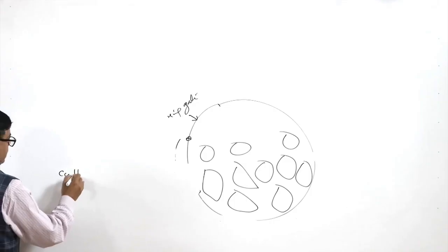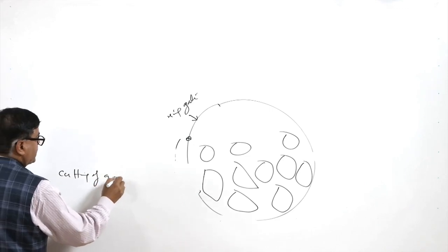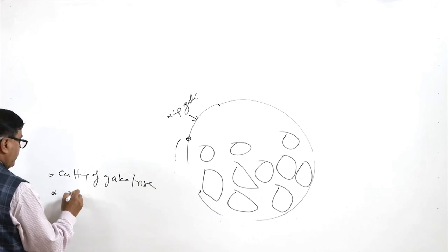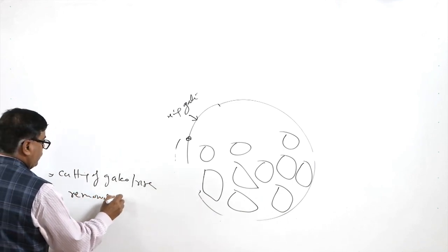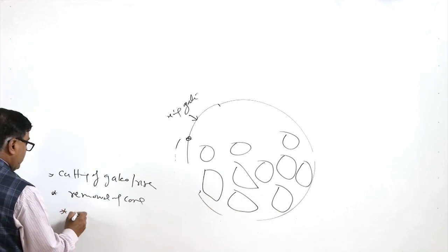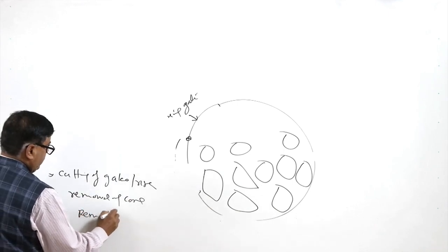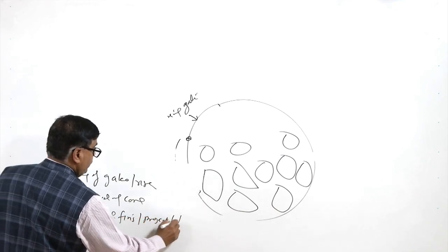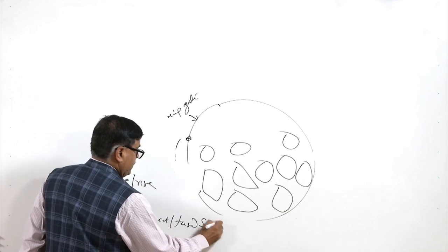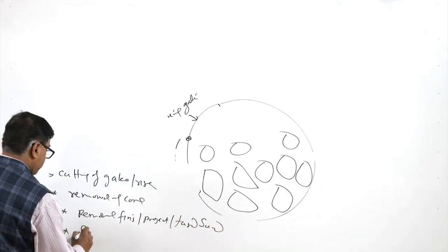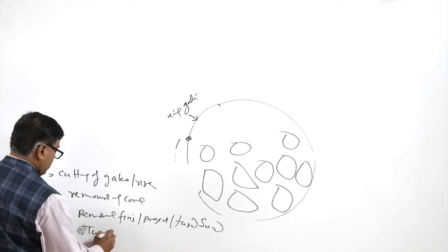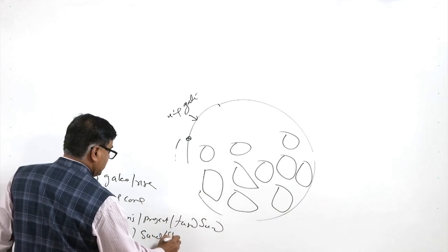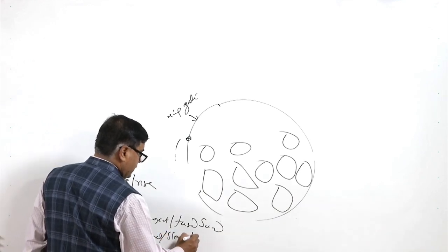the cutting of the gates, risers, etc., removal of core, or removal of the fins, projections, fused sand, and tumbling or sand or steel ball blasting.